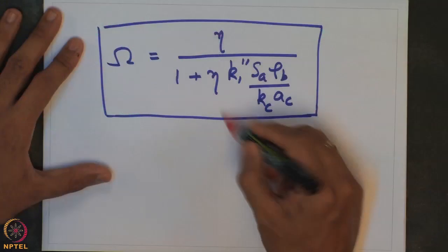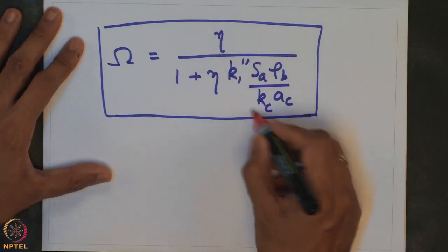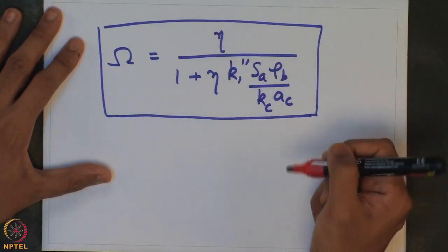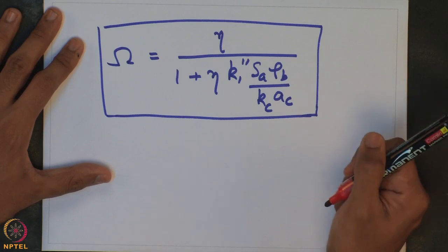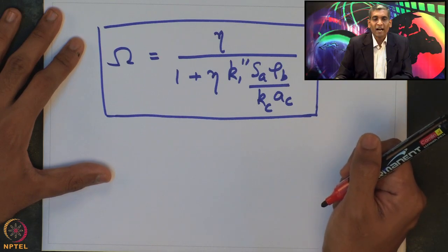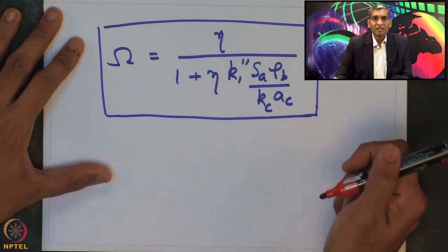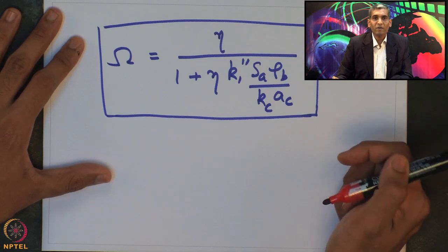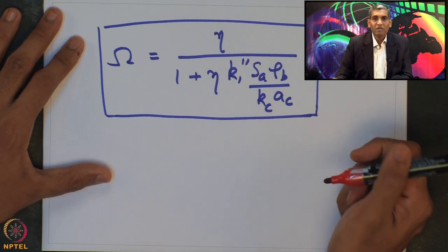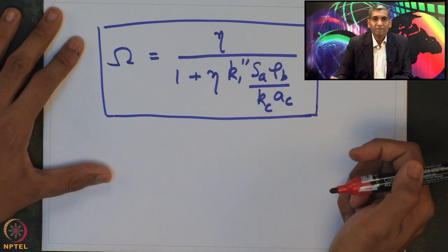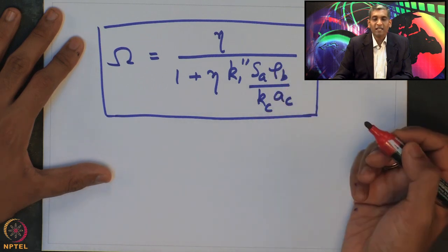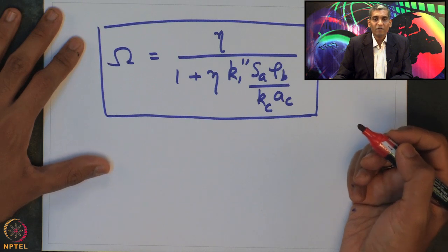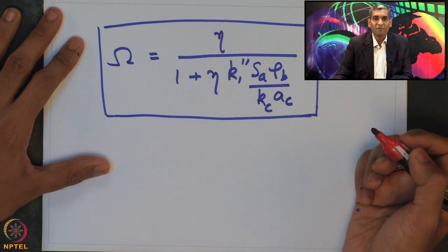So, that takes care of the resistance to mass transport inside the catalyst pellet. If I now look at the denominator here, the Kc Ac essentially quantifies the resistance to mass transport outside the catalyst pellet, that is the resistance offered to transport of species from the bulk to the surface of the catalyst pellet. So, 1 by Kc Ac quantifies the external resistance to mass transport outside the catalyst pellet.